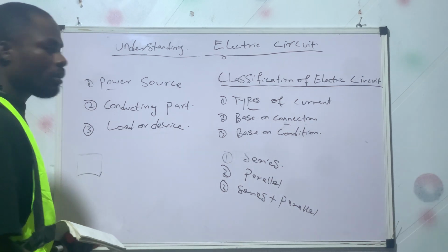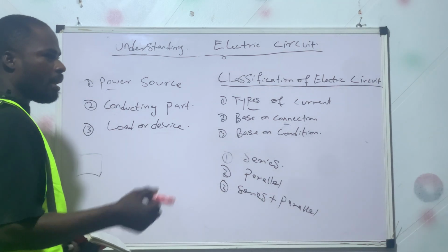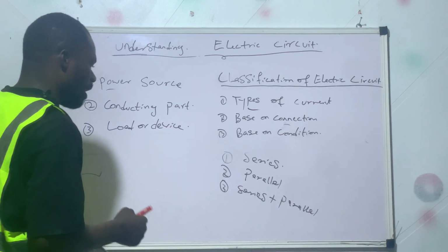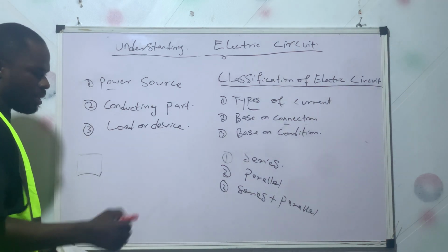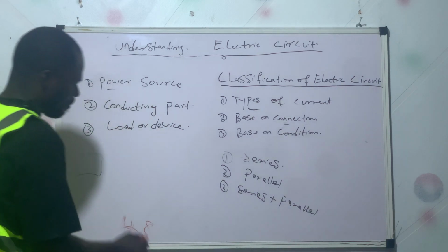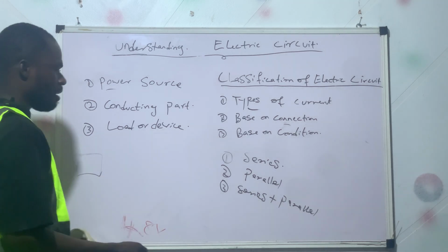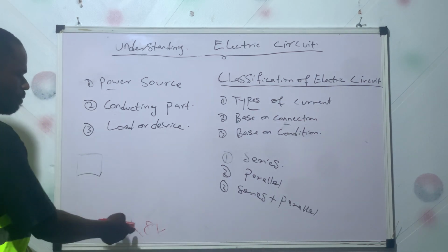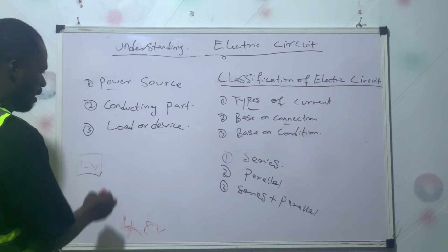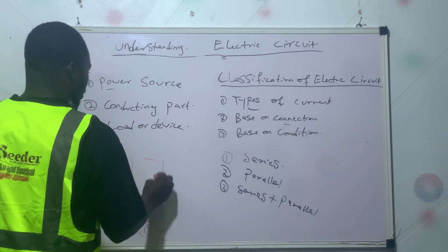For example, most inverters are rated to function at 48 volts, and some of the batteries or inverter batteries are rated in 12 volts capacity, which is not up to 48 volts, and you need to install a 48 volts inverter system. When you have a 48 volts inverter system to install, you need to make up for this capacity. So you need a 48 volts battery bank. Your battery is rated at 12 volts. So how do you make up for a 48 volt system? You will be needing 4 batteries for your setup.